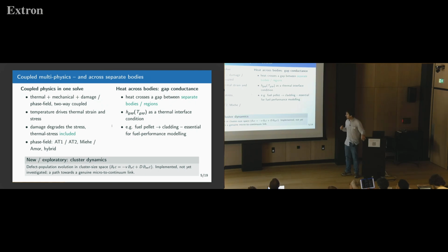Then just a word on multi-material domains, because again I started doing this to study some materials of interest for me. In particular, nuclear fuel elements are essentially a tube of metal with a set of pellets of oxide inside. So two materials, a tube and another one with a gap. And I could implement some strategy to model the transfer again among two materials.